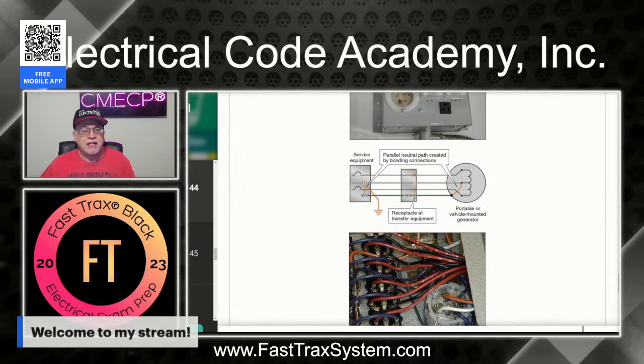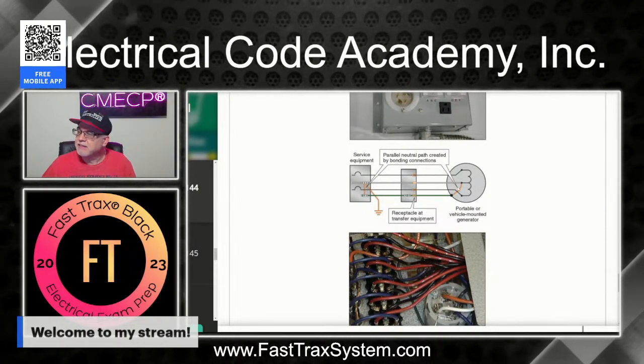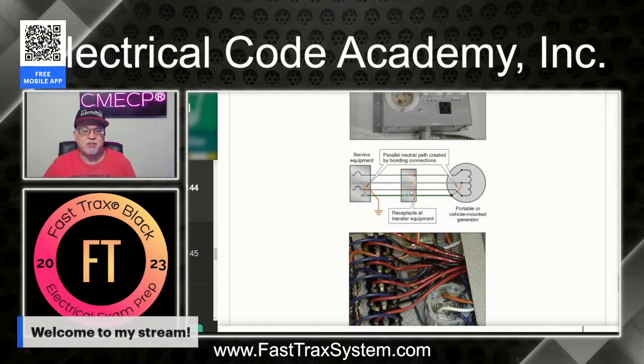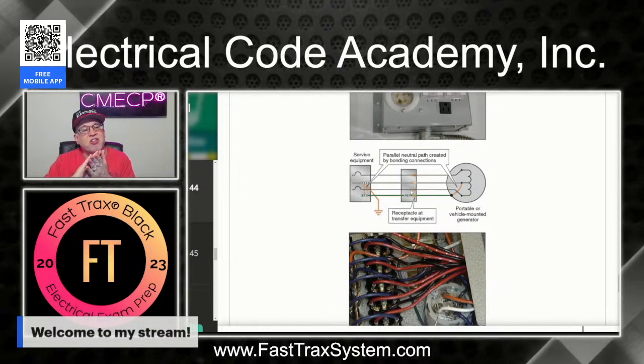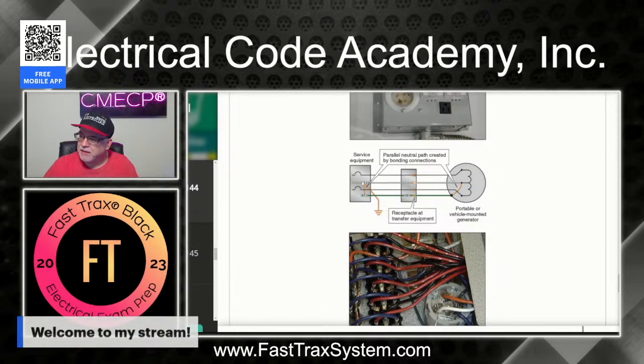So if you're using a portable generator or a vehicle-mounted generator that does have the bonding taking place in it, which is what you would use if it was a standalone, by the way, you're going to have to select transfer equipment that does what? That actually switches and shuts off the neutral. Because if you don't do that, then it's going to create parallel paths for neutral current.